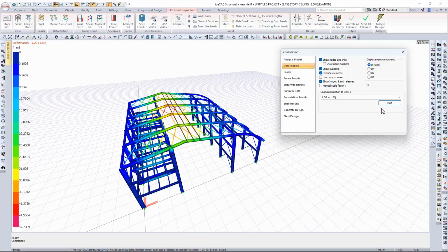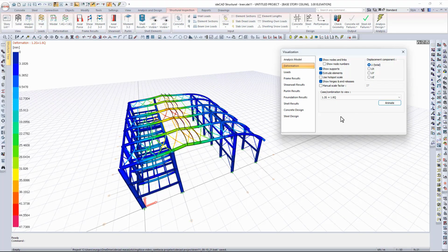Reviewing both modal and vertical deformation results is especially critical for identifying potential modeling mistakes. Because for users who are new to the software, this stage helps identify modeling mistakes, such as missing or incorrectly placed nodes, or incorrectly defined connections. For example, if a steel member isn't properly connected to its intended node, it may appear to extend infinitely in the analysis model, a clear indication of a missing or misaligned node, and a common modeling error.